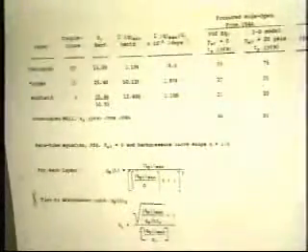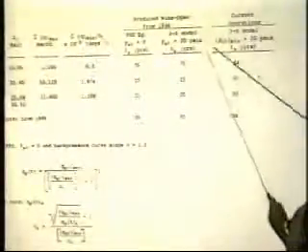I mentioned earlier I didn't have this out as a copy. My overheads. This is in a paper where we're trying to demonstrate for the 12-section study area, using the pseudo-steady-state equation with a zero flowing pressure, you get 75 years, 27, 21, or a total of 86. The 3D model with the back pressure of 20 pounds, the time to abandonment is going to be 76, 25, 20, and 82. The current operations, where you produce at a constant rate and go on decline, is 180.